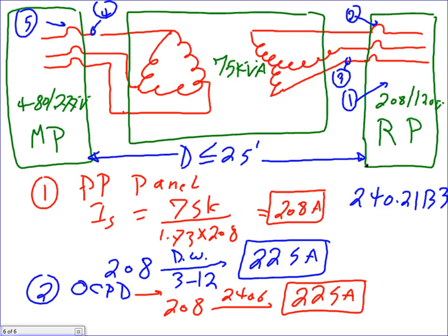The reason, if you wonder, guys, why didn't I multiply by 1.25? I told you that before, because when I size this transformer, I added all my KVA load of the 208 load, everything. I added them up and derived them, and I came up with 73 KVA. So what's my next standard?